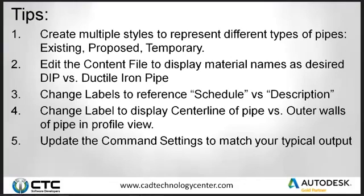So my tips I have for you to end this wonderful webinar: first, create multiple styles to represent different types of pipes. If I've got water main that's existing, make it look different than water main that's proposed or water main that's temporary. Make your styles look different. I want to be able to look at a print and say, yep, that's proposed versus existing, whether it just be the color, and when it plots out, one's light gray, one's dark gray.